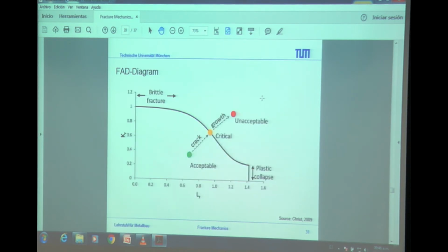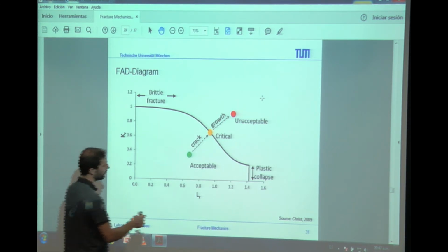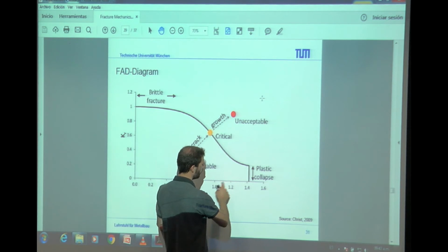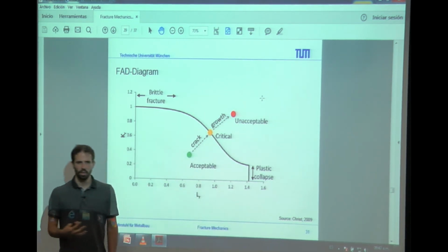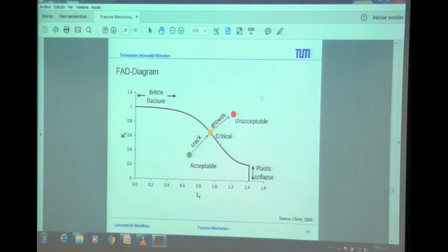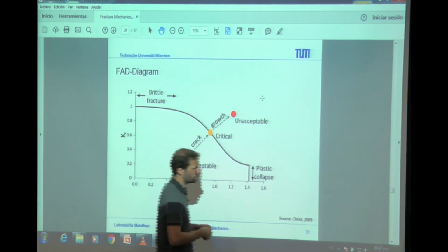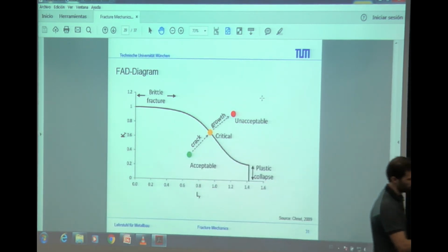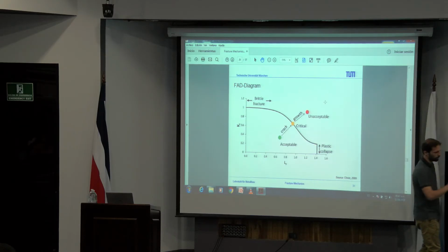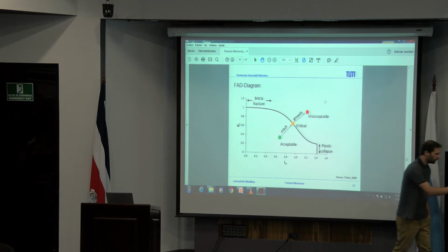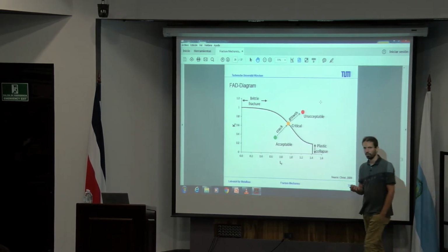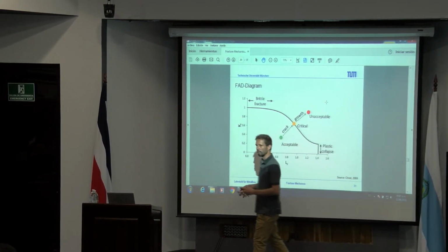If you, for example, go for the R6 concept option 2, you also get here some further information about the plasticity, about the plastic collapse, where you also take account of some strengthening of your material, and where you go also above the Fy, so above the yielding point.